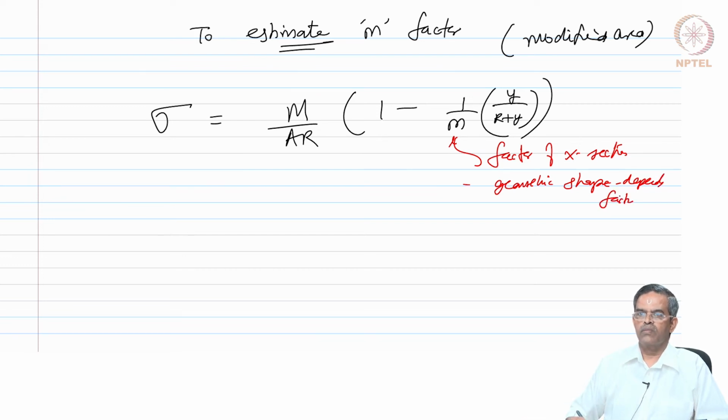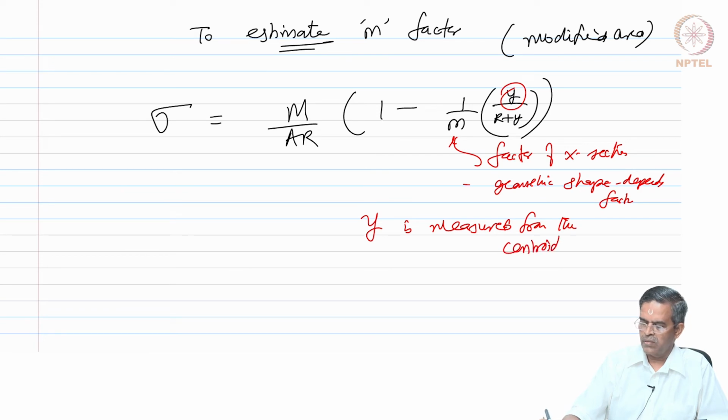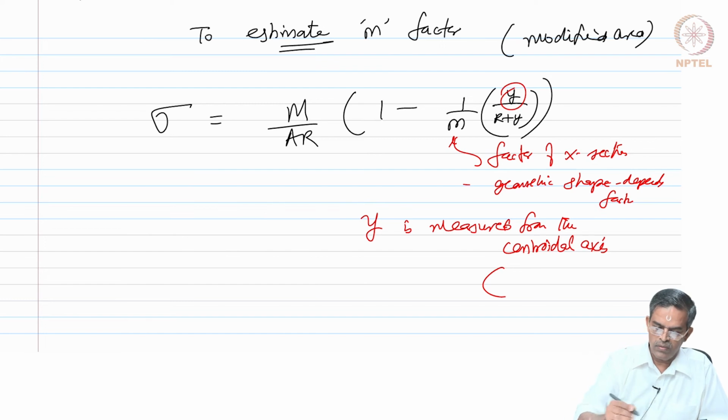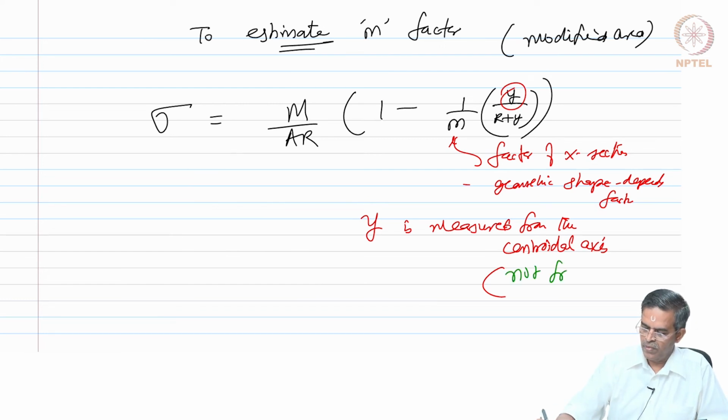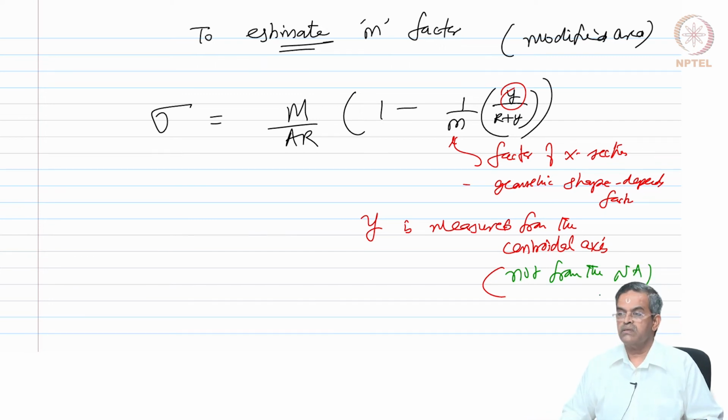Okay. Furthermore, y is measured from the centroidal axis, not from the neutral axis. You must remember this. Okay. There is a common confusion and a common mistake which people generally make when you estimate stresses.